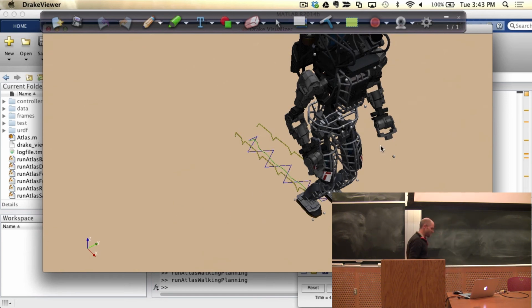So am I happy with keeping my center of mass at a constant height? Well, if I need to move on demand and don't want to wait for it, then I'm going to be happy with it right now. But really, to do more dynamic, more interesting motions, to be more efficient, or if I'd like to have a better or more aesthetic plan, then still there's a huge role for this to play, because this gives me an initial dynamically feasible plan for a humanoid robot just like that, right? And if I take that as an initial guess and hand it to a trajectory optimization that's thinking about the more complicated dynamics, removes all the assumptions, then I've already given it an initial feasible seed. It doesn't have to start from scratch. Okay.